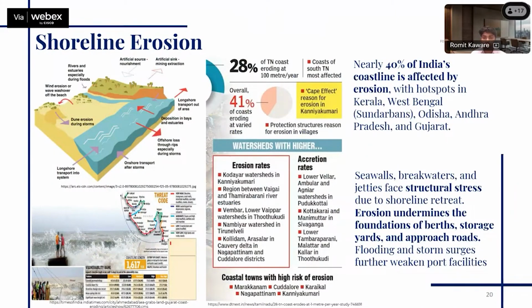Now, when I talk about sediment transport or sediment classification, we really need to look into where all of this might have practical applications. One of the major challenges that the Indian coast faces is shoreline erosion. Around 40% of the coast faces erosion of some sort, mostly in Kerala, Gujarat, Tamil Nadu, and West Bengal as well. So the changing hydrodynamic conditions lead to erosion and accretion of the sediments. Once that erosion and accretion happens, how does that sediment get redeposited?